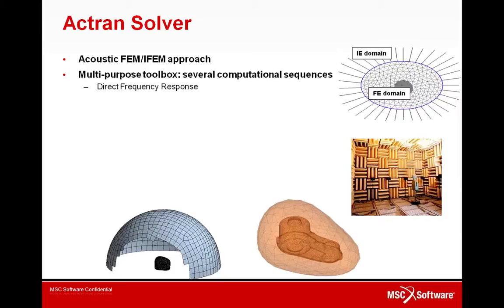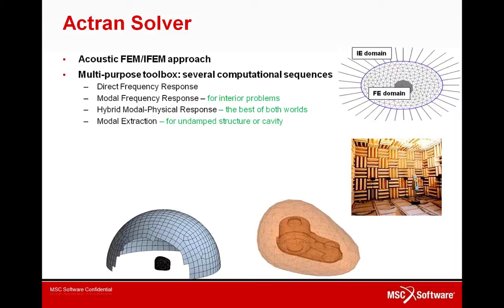There is also the modal frequency response, where the solution is computed using a preliminary reduction in the modal space. So this is very well suited for interior vibro-acoustic problems, and modes extracted by Nastran, for instance, can be used. Then we have the hybrid modal physical approach, which basically combines the best of both worlds. And in such analysis, the structure is usually represented in terms of modes, and the acoustic field is solved in physical coordinates. Then we also have a modal extraction solver to compute the modes of undamped structures or undamped cavities.